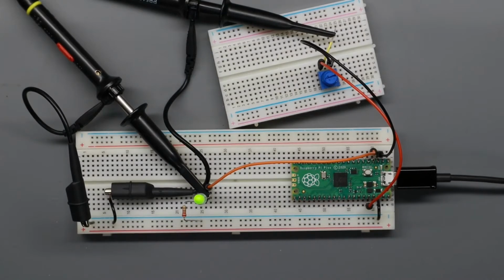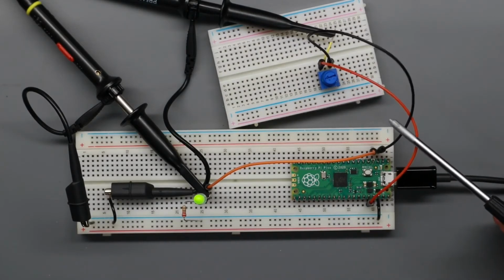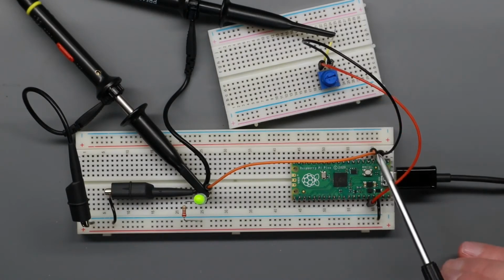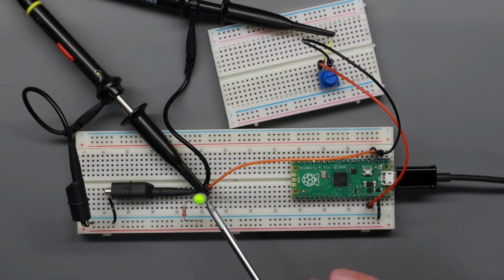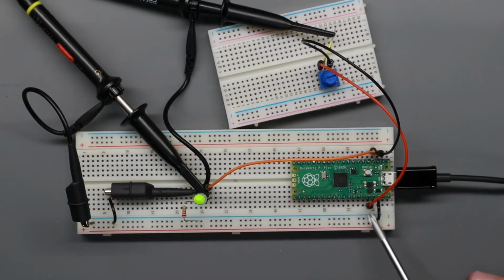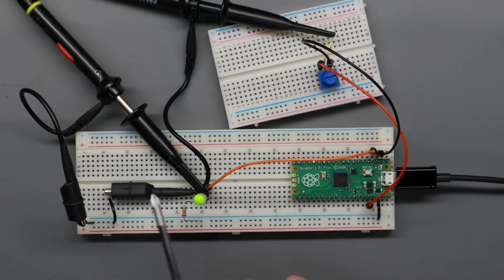Now up here on the actual breadboard in the real world, we've got the same thing going on. You see 2 wires here that were for our analog signal. This is the wire off of GP number 2 coming over, connects to the long leg of the LED. Flat side of LED always goes towards negative. So that's connected to ground via this 220 ohm resistor on the ground rail and then back into the Raspberry Pi PICO on a ground pin. And here is the ground connector for the oscilloscope and the probe for the oscilloscope.